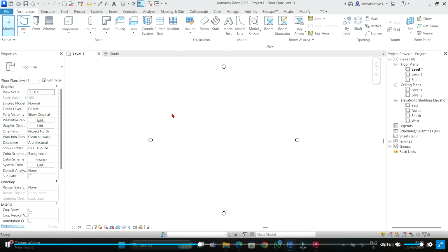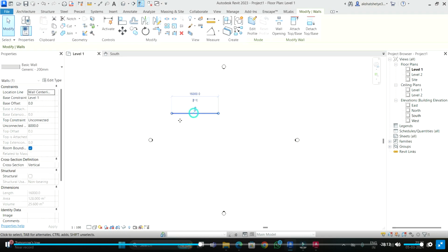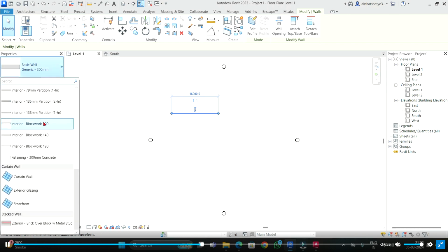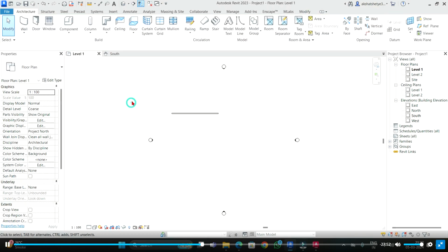So let's say I select this particular element, whatever you see in here are the properties of this element, this family. Everything is a family, so this element has its own family. It is a different family. I'll just give you a gist: you can see all these are different families and types, so you will have n number of options. Each family will have its own properties. Whatever you see in here is known as an instance property.